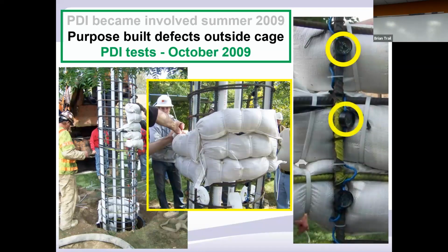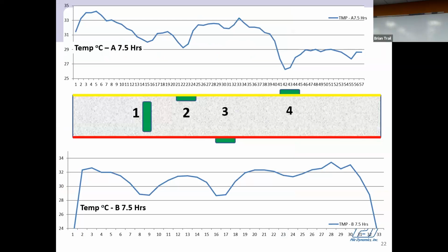Their idea was to put temperature sensors spaced apart along the entire length of the shaft and measure them continuously instead of at one specific time. So there's our prototype chain of temperature sensors, and here are the measurements that we made. In the upper diagram, we put the sensors every 6 inches, and in the lower diagram, we put them every foot.